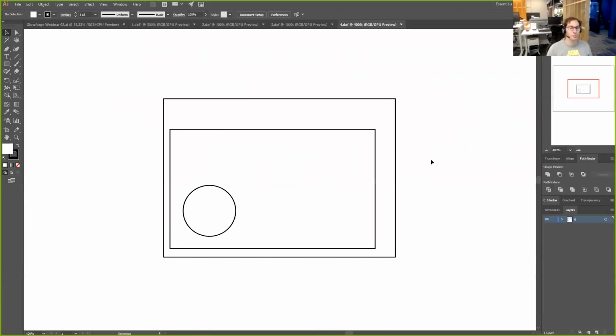So again, if you have multiple sketches and you want to send them all as a DXF, it is unfortunately going to center everything, which means the relative position is going to change. So your best bet is to have a single sketch that does everything. You could just draw everything in a single sketch and be done with it. But if for whatever reason you have to draw them as separate sketches, you can make one final sketch and project, that's the fancy word here, all of the previous sketch entities from wherever they were drawn into this final sketch and save that final sketch as a DXF, which comes into Illustrator no problem.